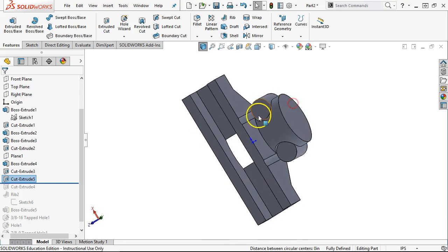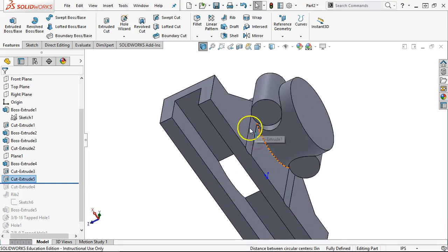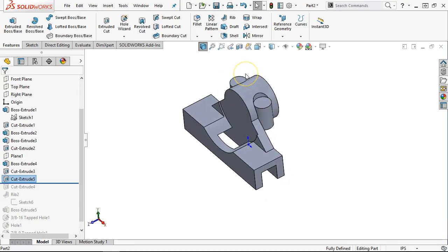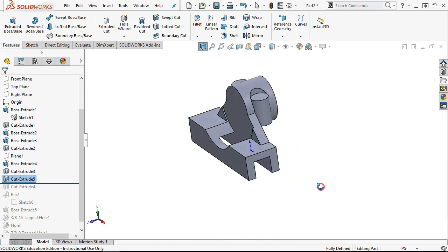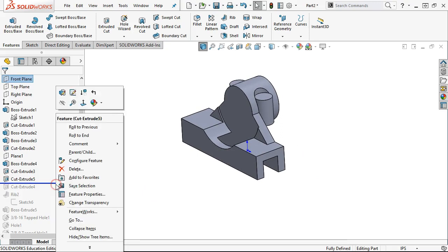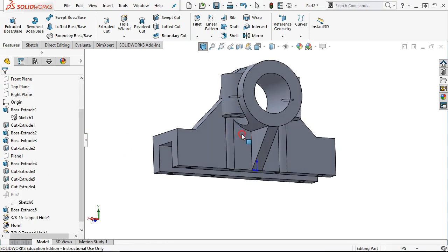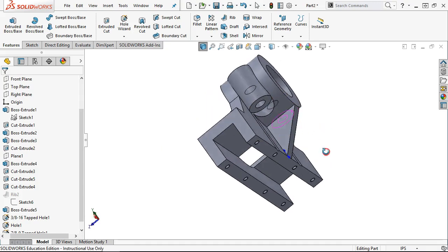And manufacturing-wise, I'm going to have to machine that. It's going to touch that wall. So the 1.62 is already on the back side, so that would be something to go back and analyze, with that dimension, 3.375 being kind of open. All right, so I think I'm going to leave that one, basically because I trust that that's going to be my manufacturing process. I'm going to have to take a long end mill and open that up.